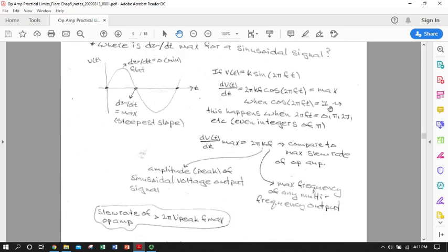So we can use that fact to define maxima of our time rate of change of voltage. Our dV/dt maxima can be expressed as 2 pi times the voltage amplitude of the original sinusoidal voltage signal times frequency. And that came right from this term right out front of here, assuming that the maximum value that this part can assume is 1. So this is our maximum. This is the maximum slope that the function assumes, right? 2 pi times the amplitude of your sinusoidal function times its frequency.